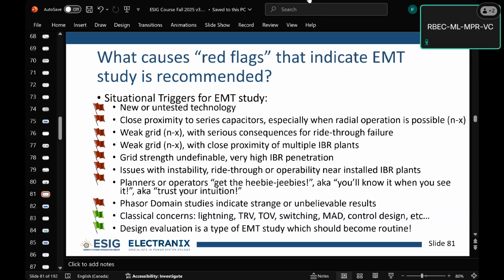For example, if you're doing anything that relates to transients, how much of the detailed IBRs do you need to model? Because you're worried about such a short time, you have to decide how quickly all of those IBR plants are going to come in and actually impact your transient overvoltage. If you model everything, it's going to be a 6-month project.